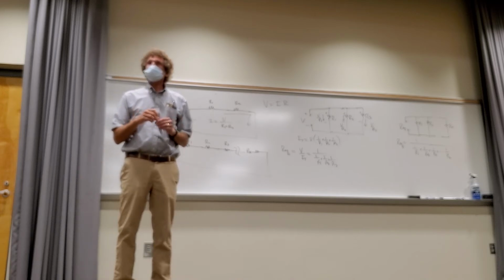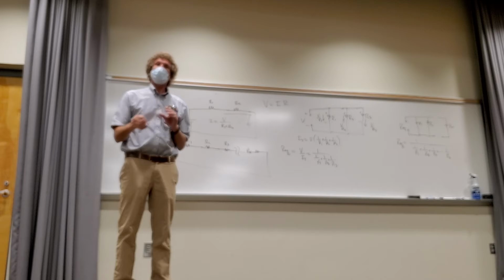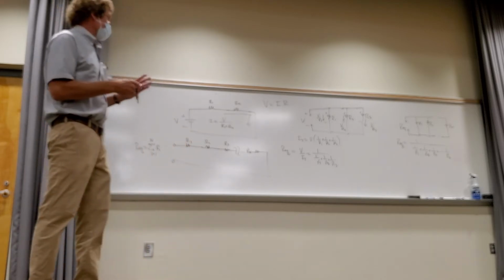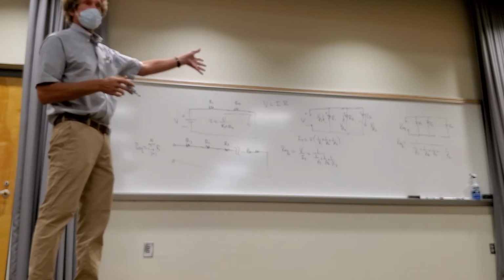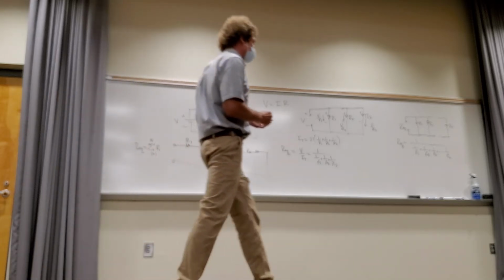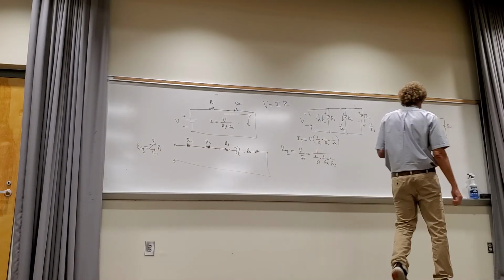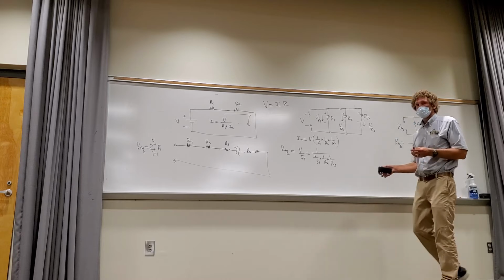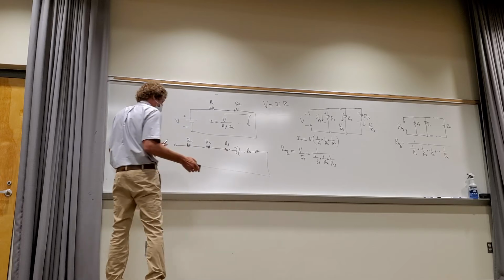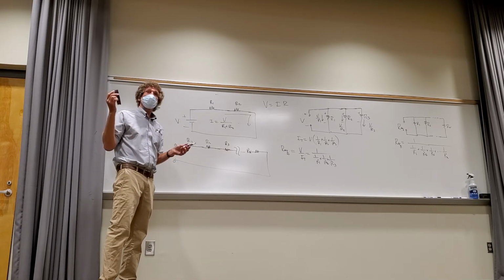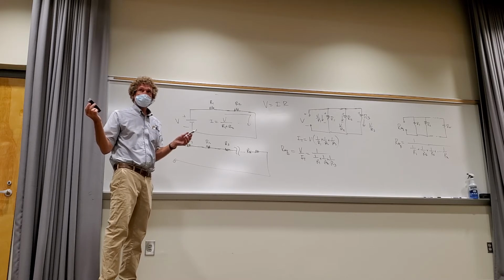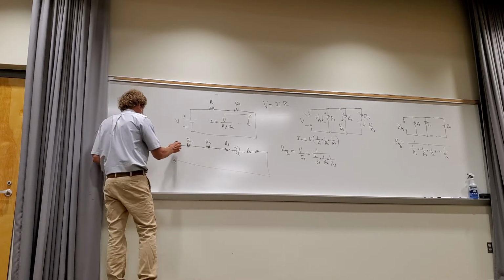So now, the next thing is, well, what if you get combinations of them? And what if they're not drawn nice and straight and clear like this? How do you go about analyzing it? There's probably a lot of schools have thought of that, but what I try to do, if all else fails, I'll use colored pens to actually indicate all the points of equal potential. And anytime you get anything between like a blue and a green would have the same voltage potential, and I could find out what it is that's in parallel and replace it by a single resistance.